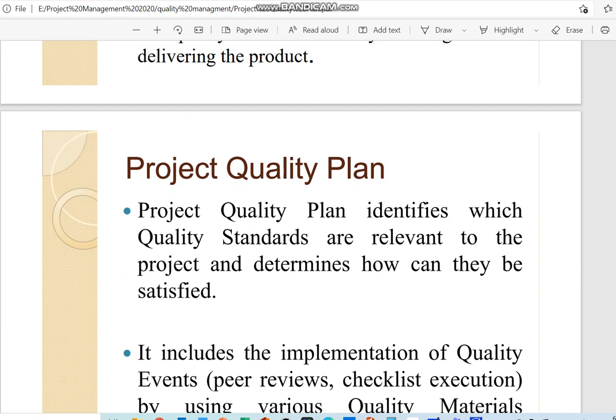Then there are bars made in Malaysia, made in KL, that have no cert. So you don't know whether it swings in from the other side of the ocean, you see. So no standard means there's no testing that has been done on it before. It may not be up to whatever requirement you are designing for in your drawings and in your calculations, you see. So you have to be very, very careful.